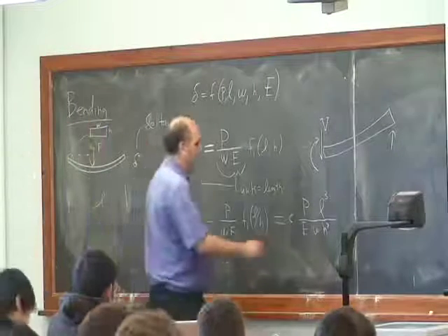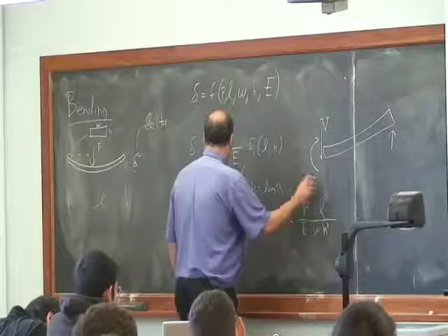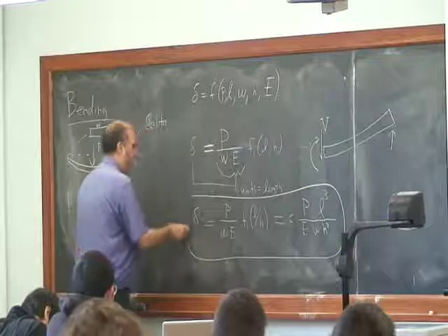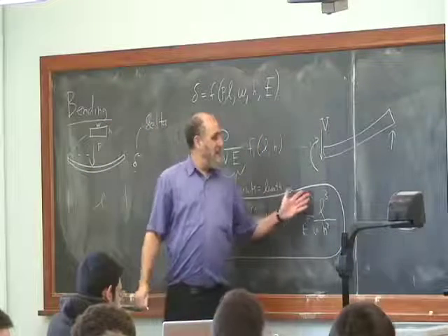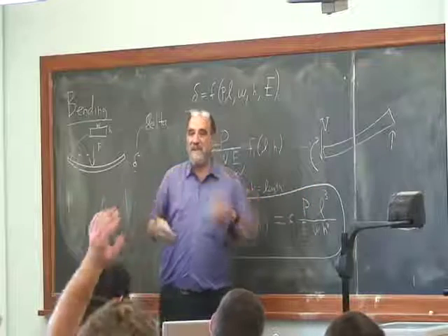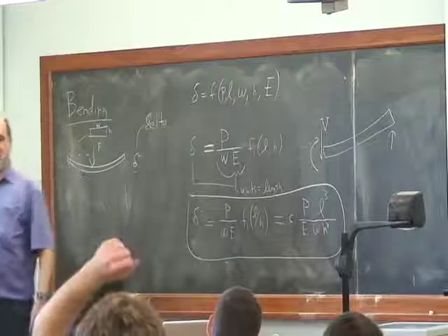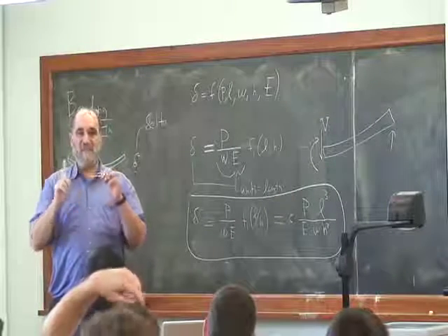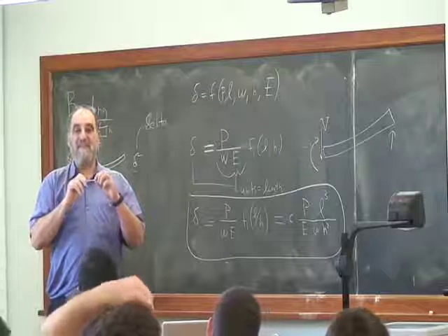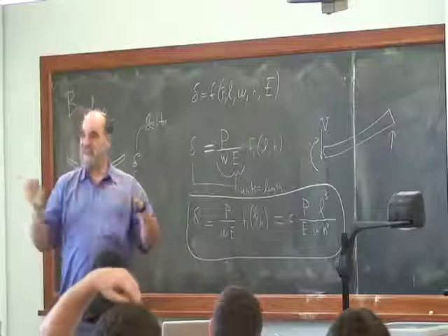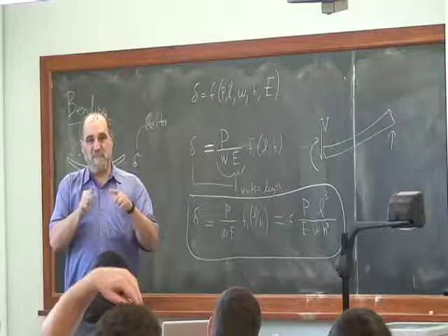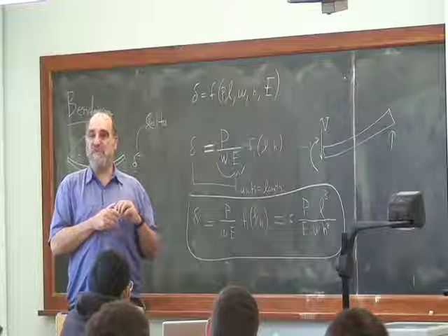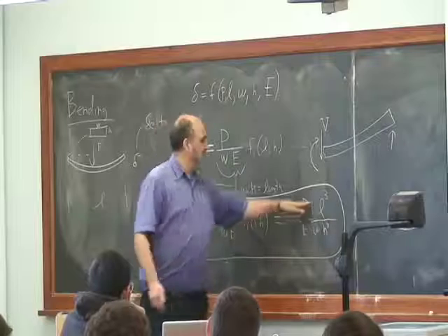What does that tell us? This is something which is good to remember. One thing is that reasoning is maybe somewhat good to remember, but there's more important things to remember as an engineer, is that when you have long, narrow things and they're in bending, they get much more compliant when they're longer. If you take your popsicle stick and look at a short segment of it as kind of stiff, if you look at one that's twice as long, it's 8 times as compliant. Which is why, for example, the swimming pool diving board, you just change the support point a little bit, and it changes the compliance of the board a lot, because the compliance increases with the cube of the length. The compliance goes with the cube of the length.